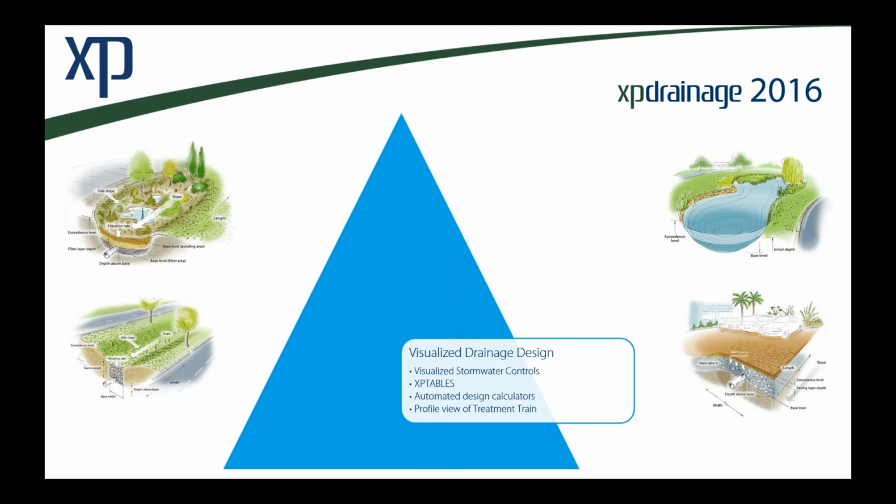So you change the size of a facility, you change the slopes, the batter of some swale. Well, it's going to show how big that facility footprint is going to be. It'll show where the layout of the pipes or channels will be. So it's very, very important to have that connection to avoid a whole range of issues. Simply put, goof-ups that could happen. Goof-ups is a silly term for what can be a very, very expensive problem.